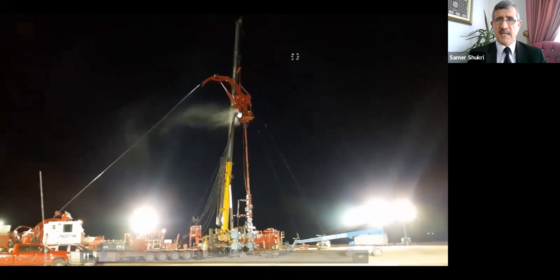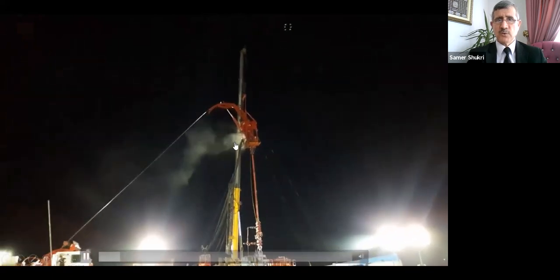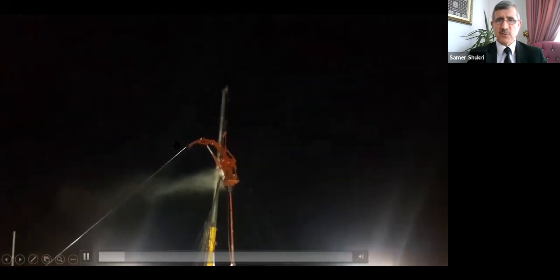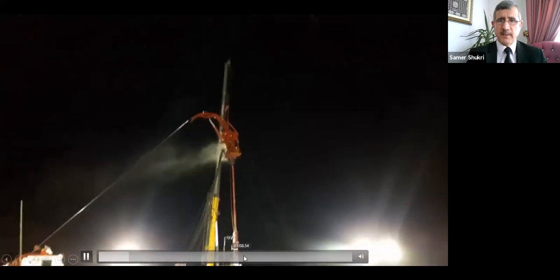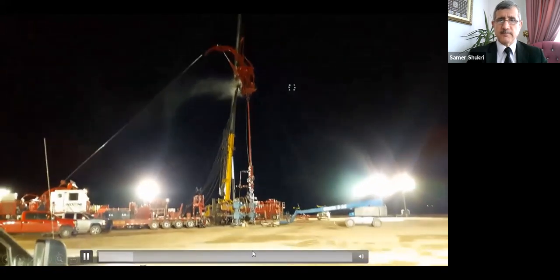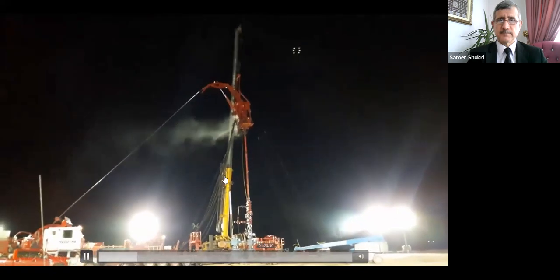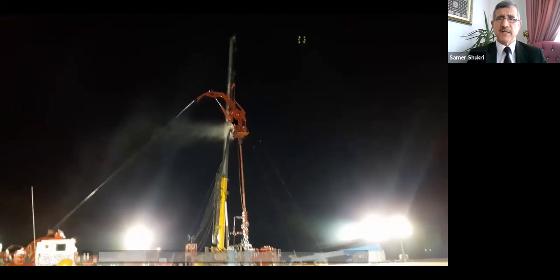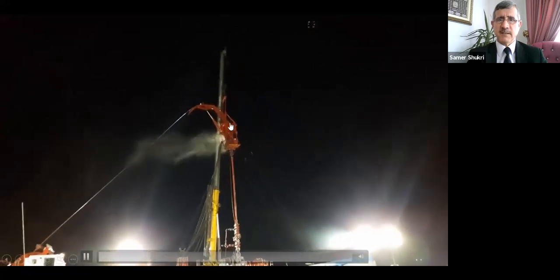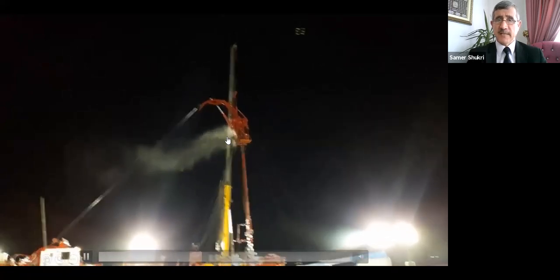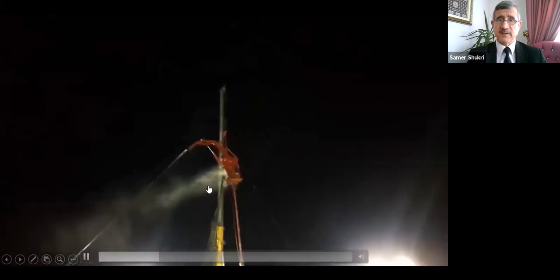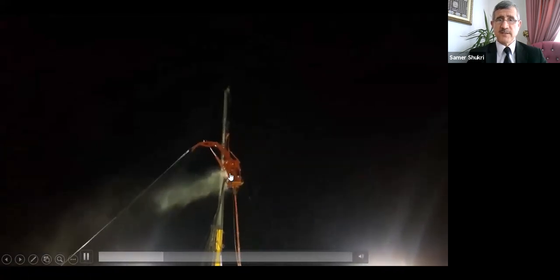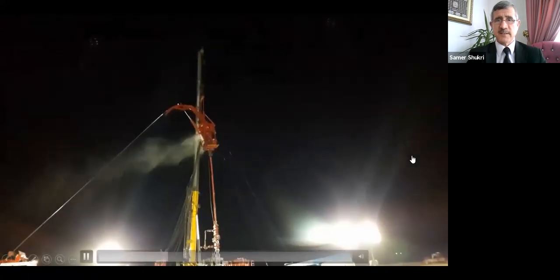You see there is gas here. So what should we do in this case? We stop coiled tubing. Yeah, this is not good. It is very dangerous, this situation. Any spark will make fire here in this area, in the injector head. And especially during the night, the focus during the night is less than during the day.